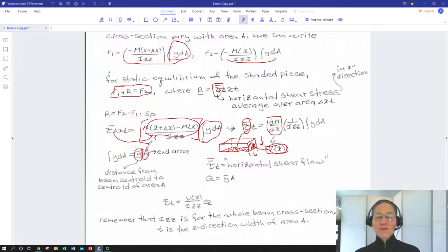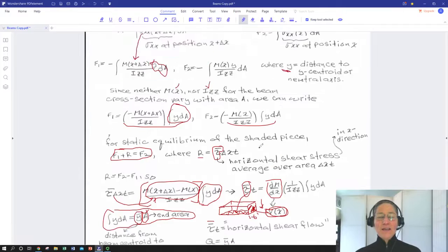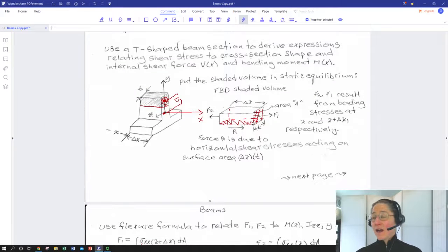We've got two factors that are going to be acting on our max shear. On the one hand, we have our tau bar. So it would be easy to say we're probably going to find the max shear out at those end surfaces as well. But when we look at how we apply this little cut section, if we envision that I want to find the shear out at this very top, I'm going to shove y bar to its maximum value. What I end up doing is creating a little teeny tiny slice up here, so area goes down. And that ends up winning out.